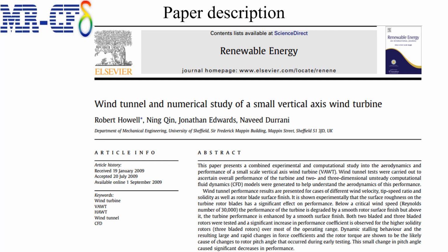In this project, the airflow enters the computational domain with a velocity of 5.07 meters per second, and the RNG k-epsilon model is exploited to solve the turbulent flow equations, as the paper stated. Also, it should be noted that the mesh motion option was enabled to simulate the rotating motion of turbine blades.